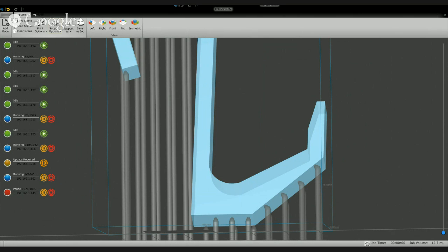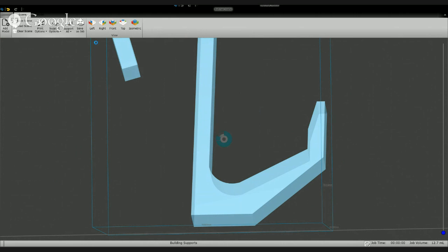And the crossbeam pullback is, if I return this to its default of 15 and increase this crossbeam pullback to 5, that's how far along the support the crossbeam is drawn. So the crossbeams were drawn at about this height, 2.5 millimeters down from the joint, and now it'll be 5 millimeters down from the joint, and so it'll be lowered a little bit more. So let's see what that looks like.